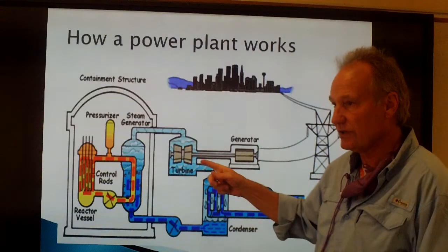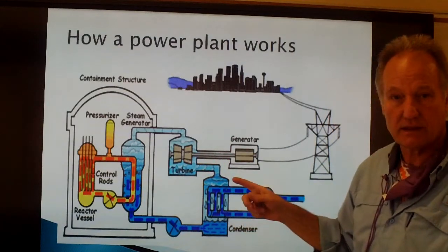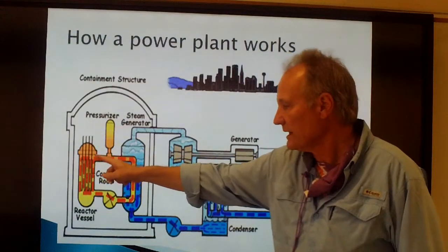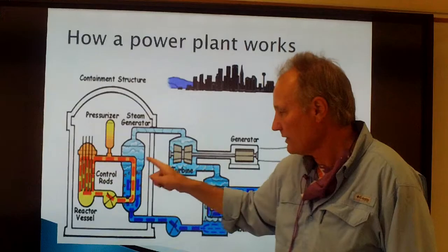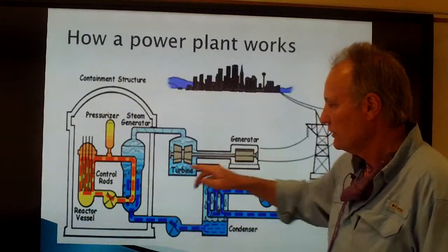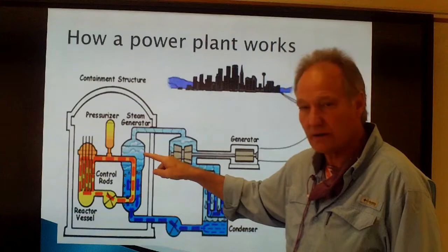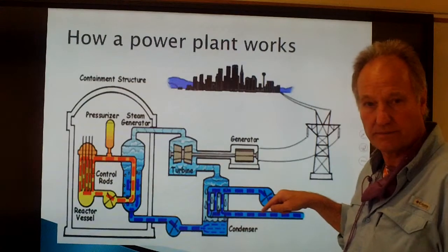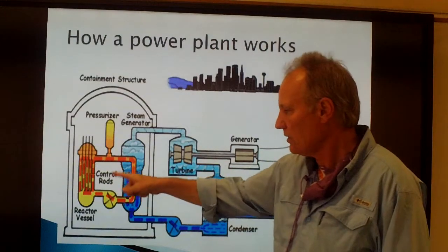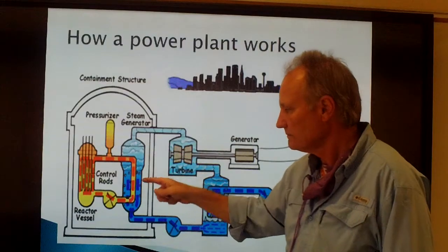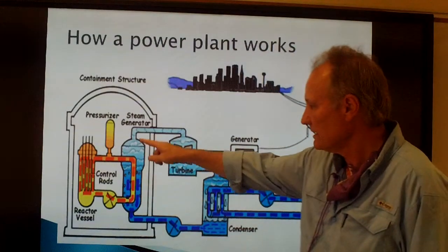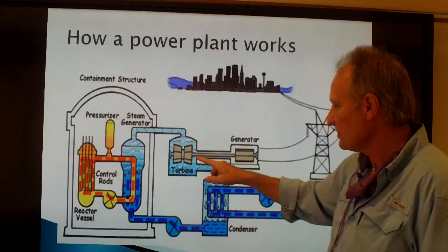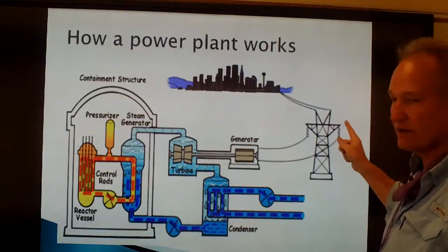Or if you go up to Duke Energy in Pickens County, it's the same basic process. We can change the heat source very easily. Make it natural gas, where now we don't have to heat up water to heat up the water. In this case, we're going to just have boilers underneath the water, and that's going to heat up and run this system. So we take one little step out of there. Same thing with coal. But the process is the same. The water turns into steam, is heated up. The steam is under pressure, drives a turbine, which then spins a generator, which then generates electricity.